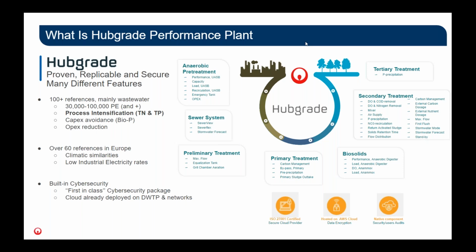The DO and nitrogen removal, that's sort of the real low-hanging fruit. Our aeration systems are the largest power consumer. Our nutrient removal needs, our nitrogen, our phosphorus effluent requirements are very critical and becoming more stringent every day. So we're focusing here on the really main core feature with that DO and nitrogen removal. But all those other features would continue to enhance the control and really work together with the DO and nitrogen removal feature. As I said earlier, this isn't anything new.